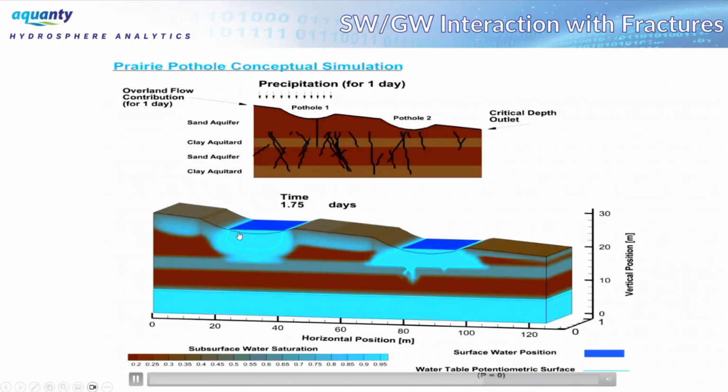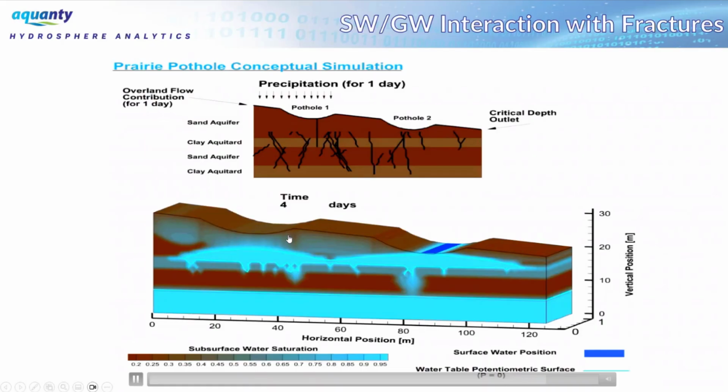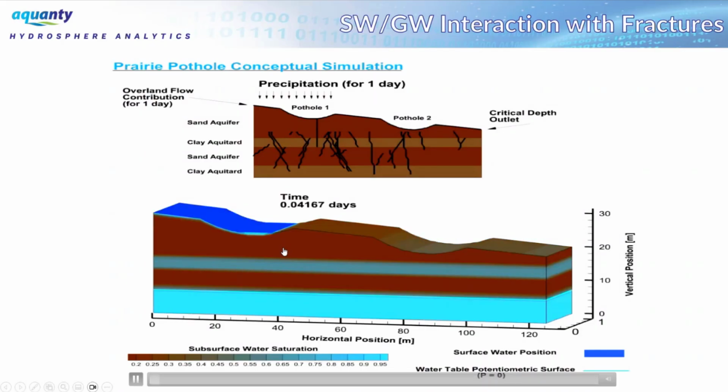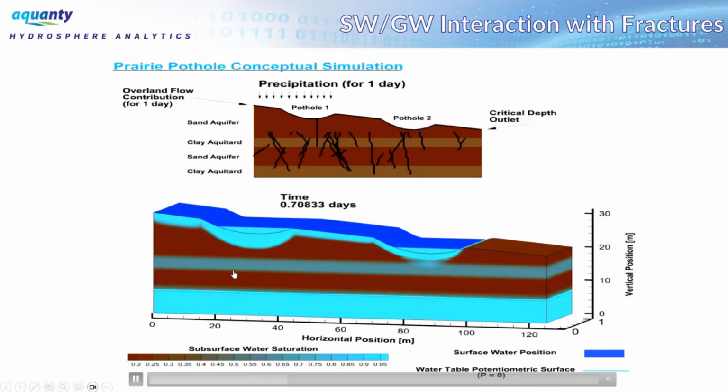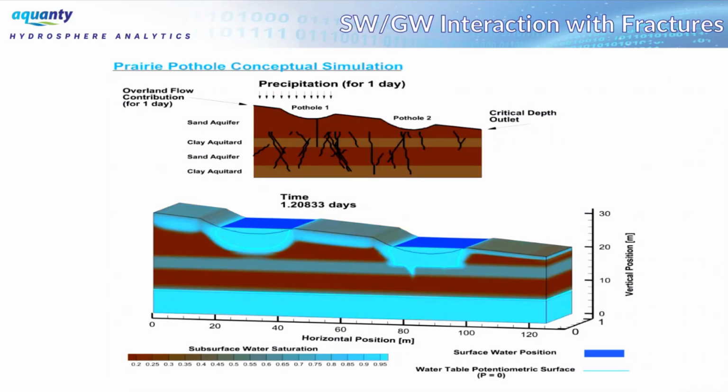If you can accurately represent the topography or the bathymetry of the location of a lake, then that lake should appear as a product or an output of your model. As long as your climatology is right, you're applying the right amount of precipitation to the watershed, the physics of water movement will reproduce the actual surface flow network.